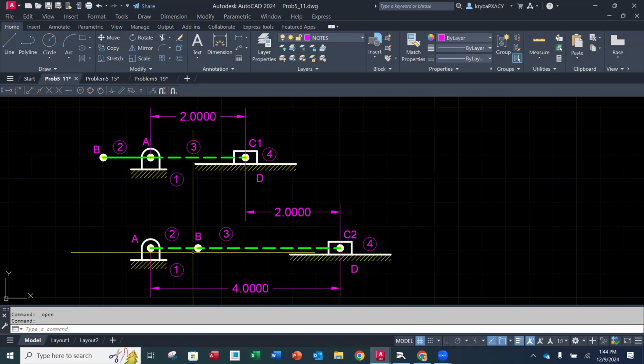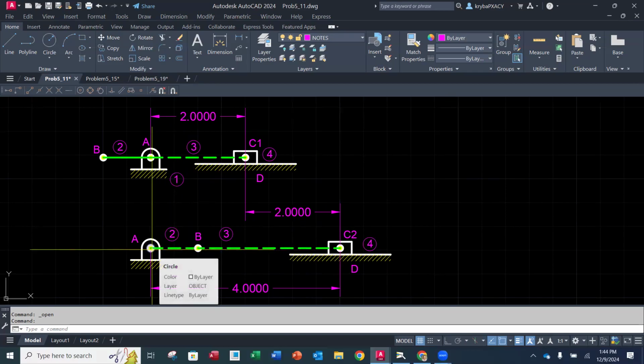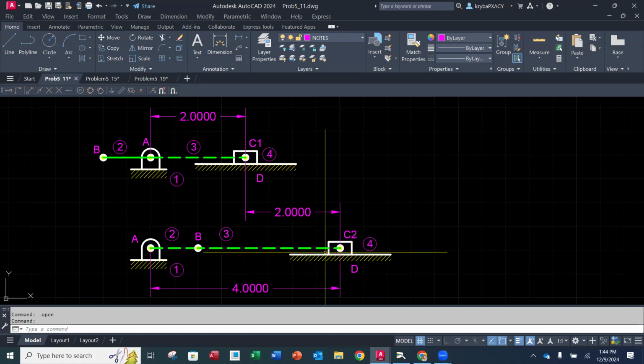My distance of L3 is 3 inches, and my crank length L2 is 1 inch. So this total is 3 plus 1, a total of 4, okay? From the center of rotation when 2 is in line and laid out with 3. Does that make sense? At the top here, this is where 2 is at, if you would, the 180-degree angle.